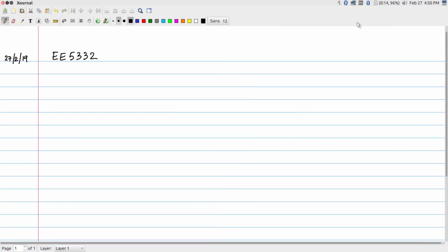Okay, so we are going to continue from where we left off the other day. What I'm going to do is quickly, once again, go over the implementation of the biquad filter in a folded architecture, at least some parts of it, so that we can review some of the decisions that were taken, and how the architecture and the choices of scheduling instances that we make translate into the hardware implementation. So to do that, I'm going to quickly redraw the circuit that we started with.